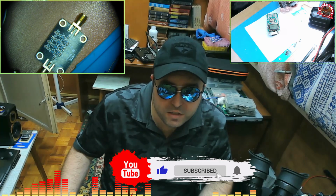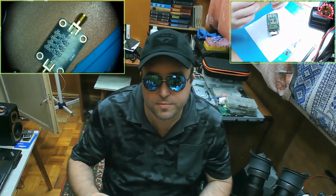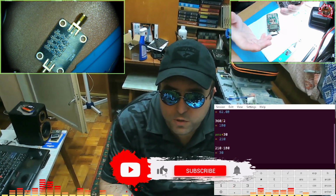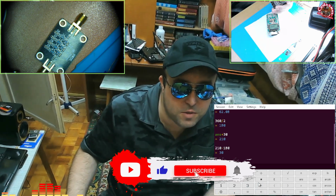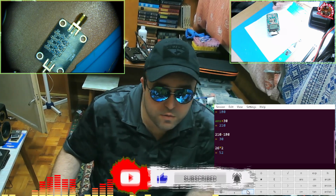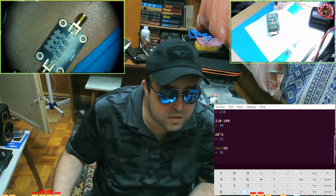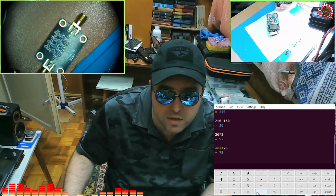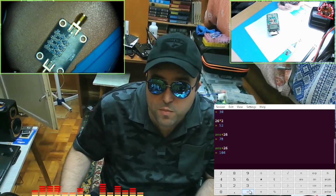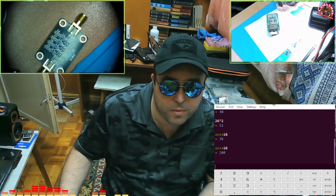Basically, the internal clock is at 26 megahertz, and the 26 megahertz it always receives. Also, it receives anything 26 times 2, right? 52 megahertz plus 26, 78 megahertz plus 26, 104 megahertz, etc, etc. All those frequencies are dead frequencies.